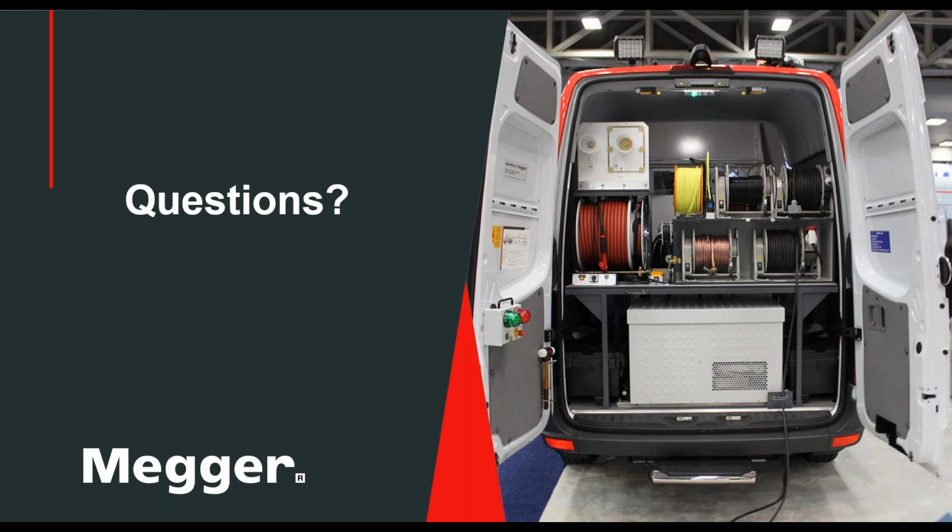The joules are a result of two things, the voltage and the capacitance. Now, the capacitance that you're working with is fixed by the particular thumper that you've chosen to use, and of course the voltage is adjustable.